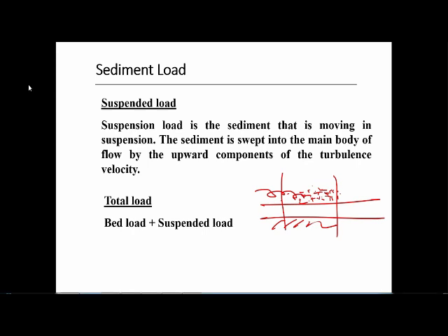That is the case if you have a separation between the bed load and the suspended load. There are also theories that simplify the equation by not taking into account the bed load and suspended load separately, but generalize it into one equation to compute the total sediment load.